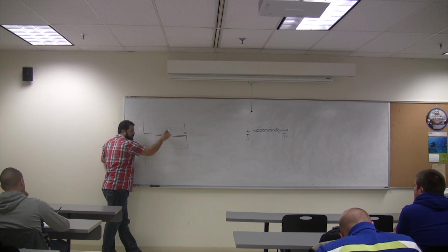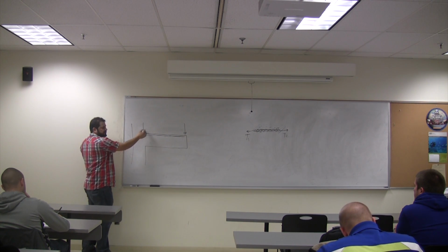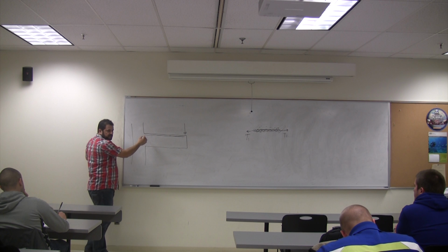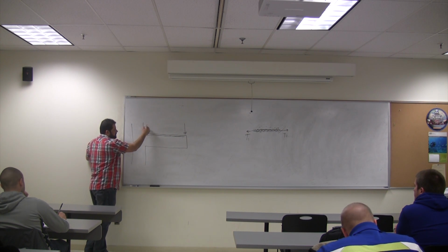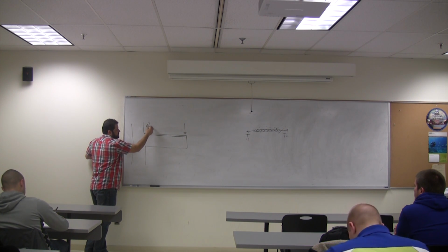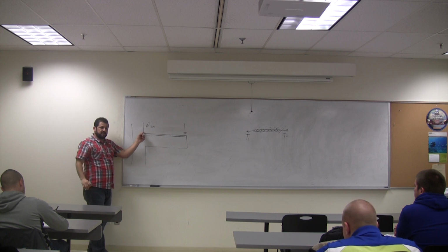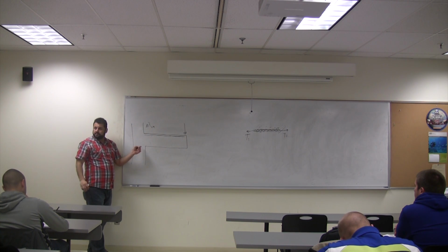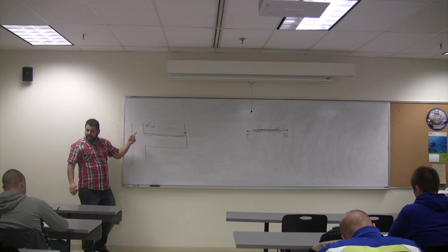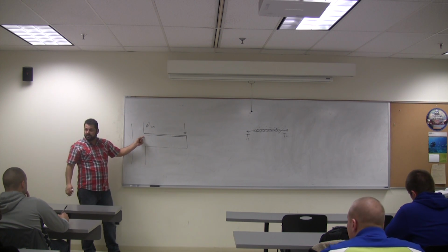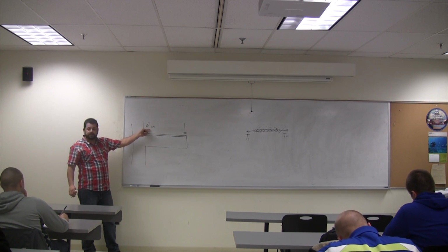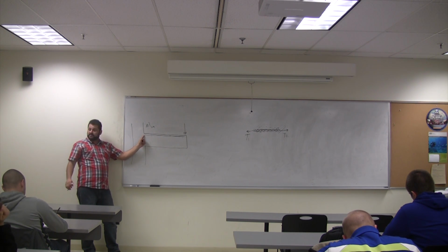When you design this cantilever beam, you take your moment. For what moment do you design? For the maximum moment, right? Which is here, the cantilever. So when you design these bars, the number of bars you need in here was based on the maximum negative moment. So do you leave them like this?